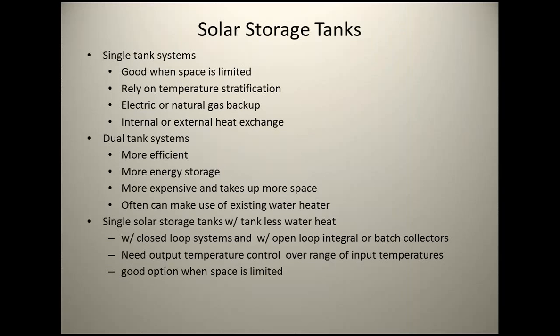Okay, solar storage tanks. We've already talked mostly about this. Single tanks are good when space is limited. They rely on temperature stratification. The top of the tank gets hot, the bottom of the tank is cold because it's got cold water in it. You put the heating element at the top of the tank, so you're not constantly trying to heat the cold water at the bottom of the tank. The water from the city comes in at the bottom of the tank.